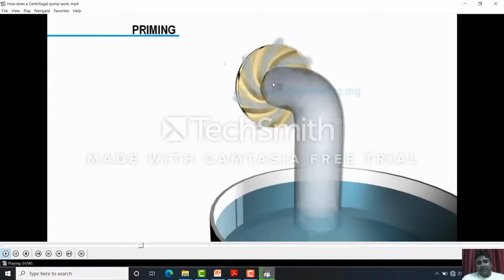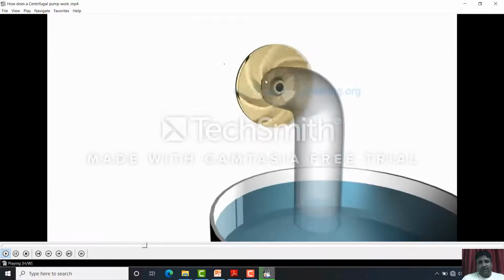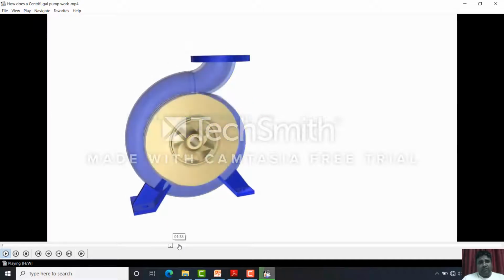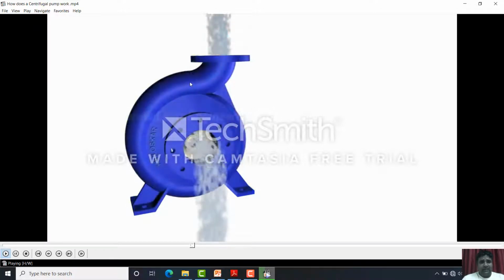If no water has entered inside this chamber, then negative pressure is not induced, and air is retained at high pressure. It is too small to suck fresh water inside the casing. So when it is expelling the water to the periphery, you can see the space between the blade and casing is continuously increasing in the same direction as the rotation of the impeller, just to tolerate the discharge pressure inside, and finally the water is discharged from here.